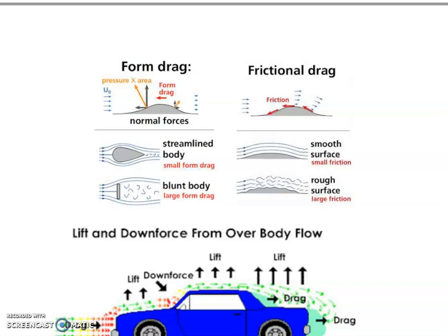Frictional drag or surface drag. It is a frictional resistance that results from air passing tangentially along the body. The velocity of air produces a thin layer called the boundary layer next to the vehicle body, which slows the velocity of air due to tangential friction forces.